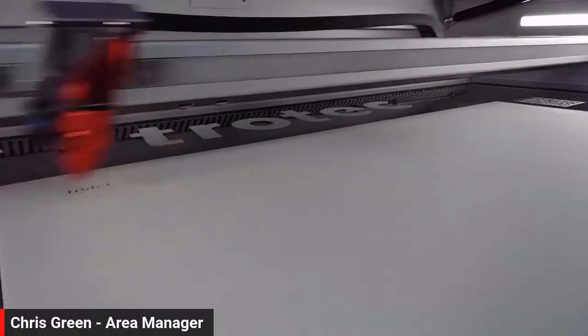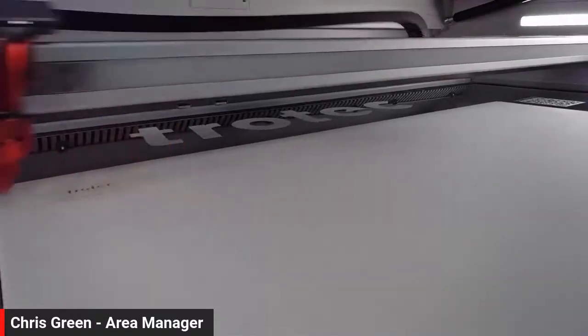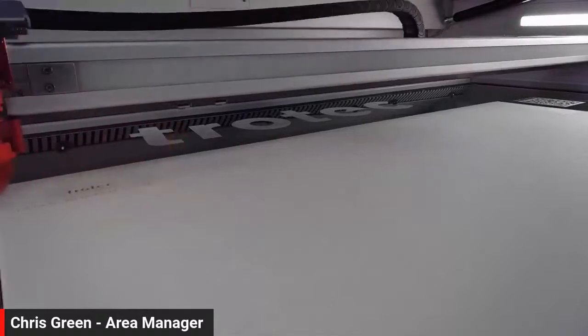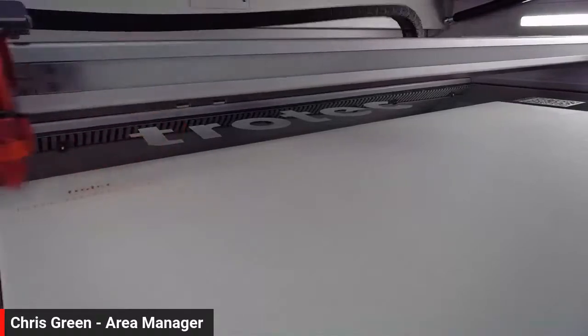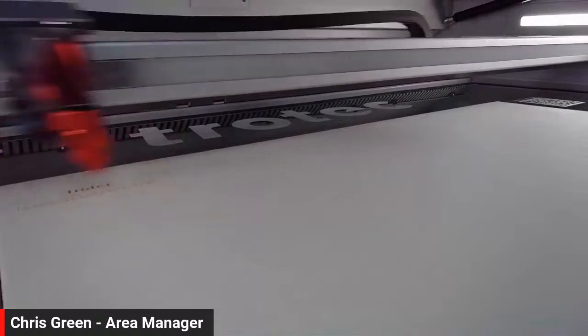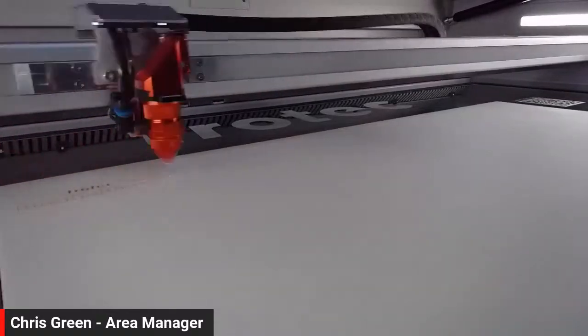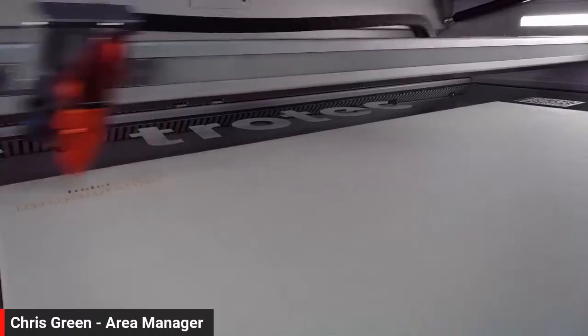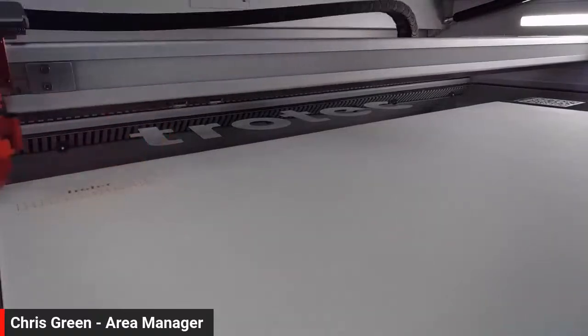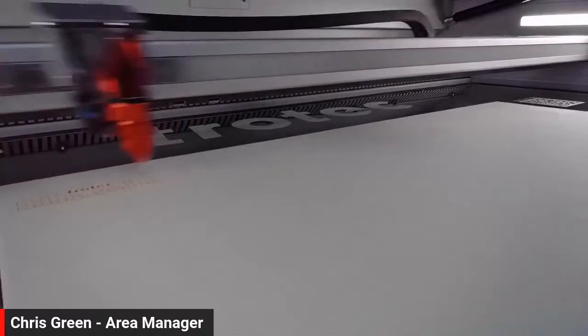Okay, so we have pre-worked on these settings. We have a generic setting for plywood. Here I've got a Speedy 400, 120 watts. We're doing the blue engrave at 100, 100. The black, which is our bigger text, at 180% speed, because we're running less resolution, so we just have to slow that down slightly just to get a bit of depth and a bit of color onto our material.